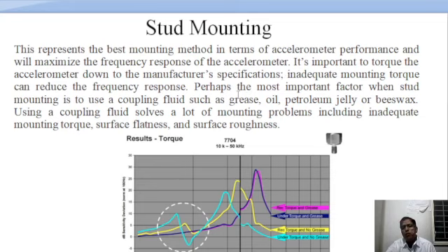So when you mount your accelerometer by using a stud, then a proper torque and proper greasing have to be maintained, and if you use a proper torque and proper grease, then your resonant frequencies can be kept at a higher frequency level. So it is always recommended to follow the manufacturer's instructions.